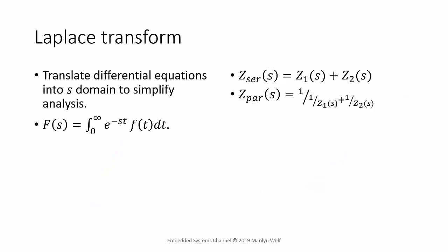The Laplace transform is in fact a general tool that allows us to represent RLC circuits in a very general form. We translate the differential equations into what's known as the S-domain that allows us to simplify analysis. Mathematically, we use an integration in order to transform from the time domain into the S-domain.